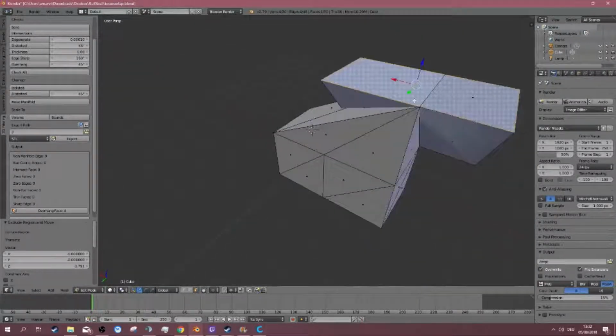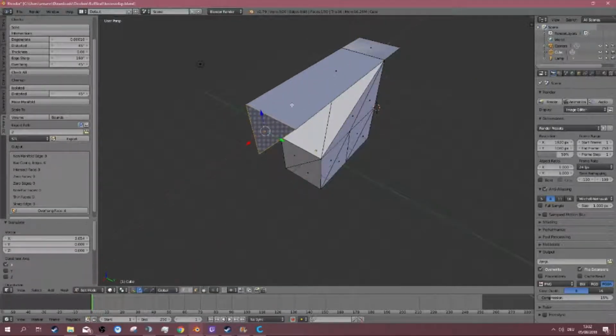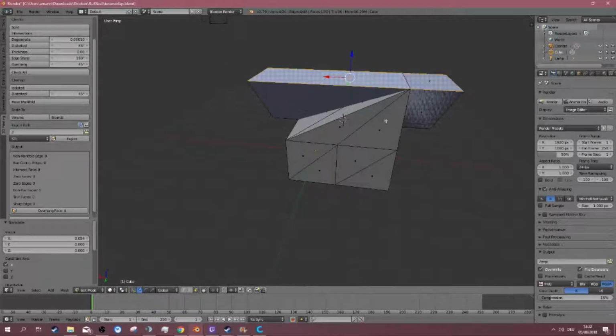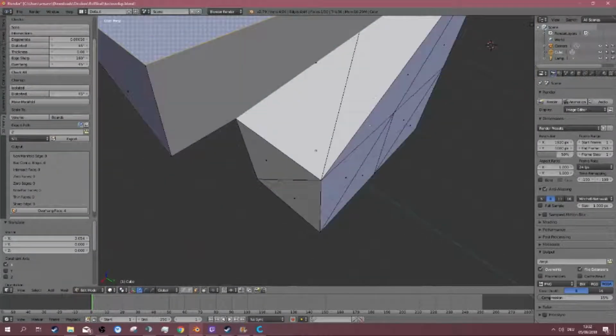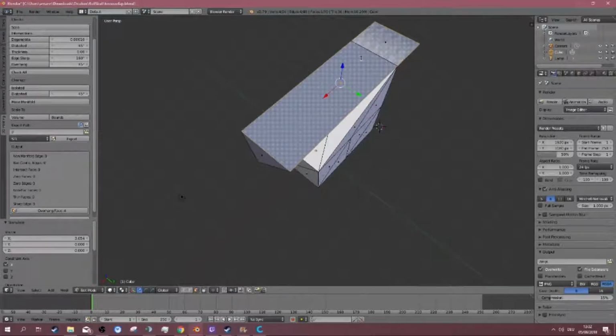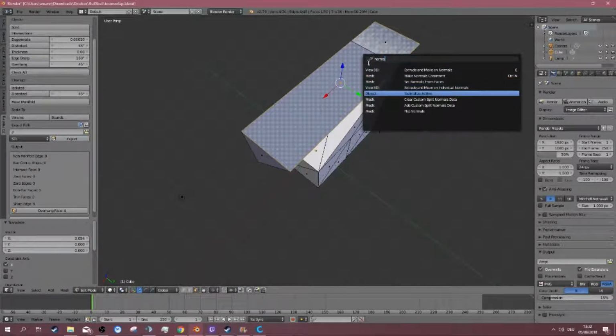And if you want to get rid of them, you can change the direction of these faces, because they are sometimes not rendered in Cura properly, or also make missing lines in Cura. So you press space, then you go to normal, and you can go flip normals. Then you just change those sides you have selected.